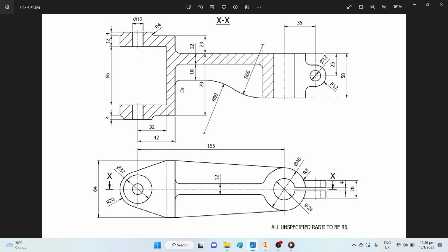The hash patterns on the part remind us of the cutting plane that touches the material that goes across. There is no hash pattern here because there is a hole. There is no hash pattern here on the tab because the cutting plane does not touch the tab at all, as it goes through an empty space. According to drawing conventions, ribs or webs are not hashed at all, so that's why you see a rib over here. And how do we go about approaching this problem?